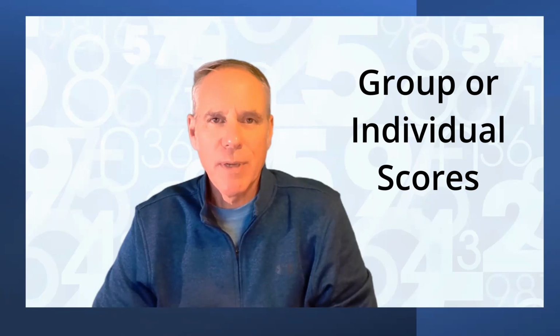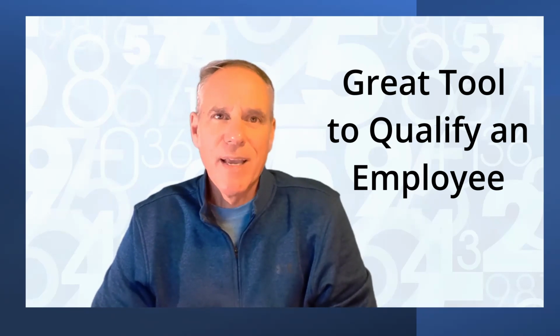What's nice about the Minitab Kappa test result is that you can see how everyone does individually compared to the known standard. If someone's not aligned to your subject matter experts and their assessments, then you'll need to retrain that individual. And what's cool too is that when a new person starts, they can read the workmanship standard and then assess the samples and be entered into Minitab and get a Kappa score. And if they pass with a result of above a 0.7, then they can be considered qualified for that particular visual inspection.